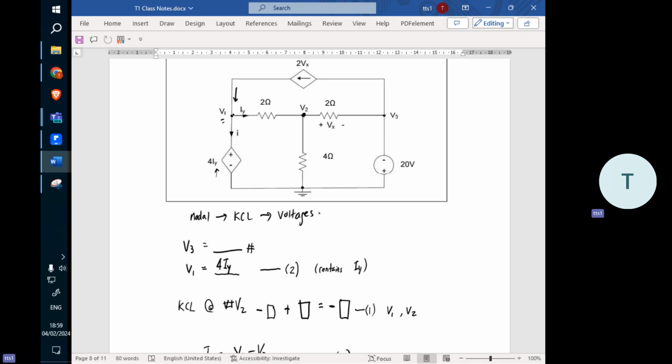You determine the V1, V2, V3, V2 to ground. So we have the voltage across here as V1 minus V2. The voltage across here is V2, V3. So here's one current. We presume the current flowing down. We presume the current flowing this way. Another current, let's say we presume it flowing this way.